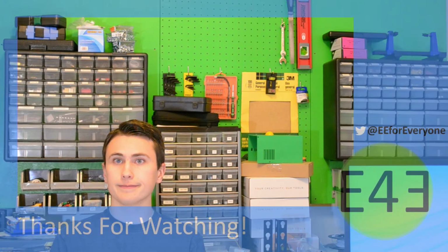This will give some time for bugs to be exposed in the code as I gain more experience with the lamp and introduce a few key features that this lamp can benefit from, such as using the battery-backed SRAM as memory with more endurance than the EEPROM to recover from power outages more gracefully. We'll also add some monitoring of the speed of the fan so that we can know if the fan's actually spinning when we turn on the 12-volt rail, to help prevent thermal runaway in case the fan were to fail.